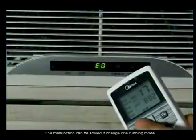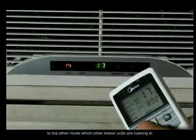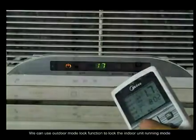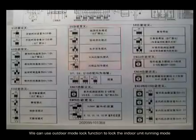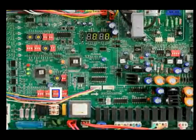The malfunction can be solved if you change one running mode to the other mode, which other indoor units are running in. We can use outdoor mode lock function to lock the indoor unit running mode. That will help the customers operate more conveniently.